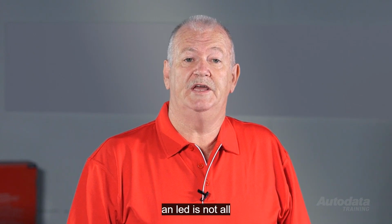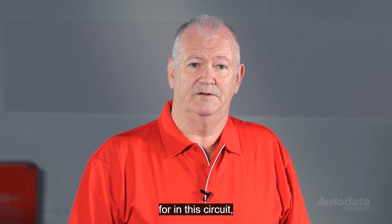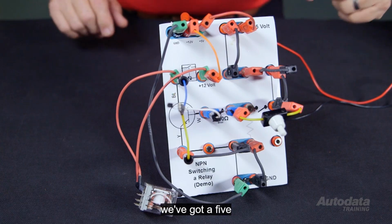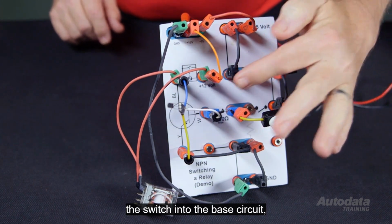Turning on an LED is not all that impressive. What else can we use transistors for? In this circuit, we are using an NPN transistor to control a relay in the same way a module would. We've got a 5 volt signal circuit going through the switch into the base circuit.